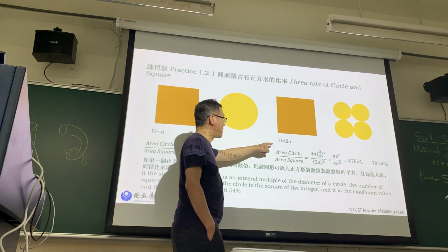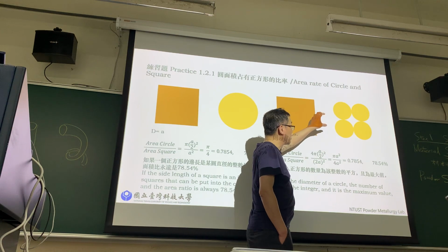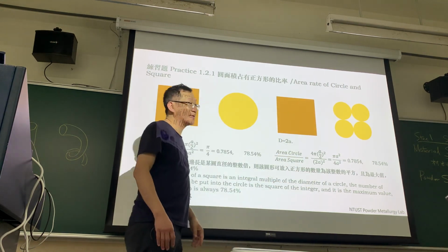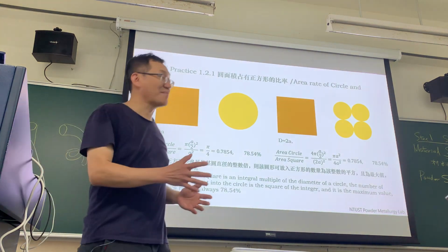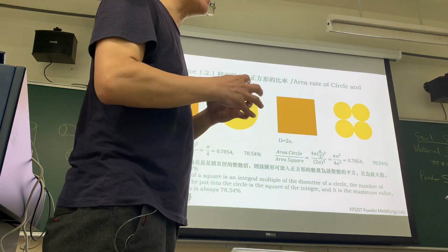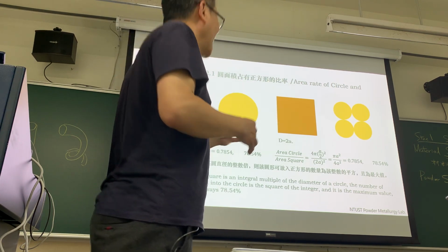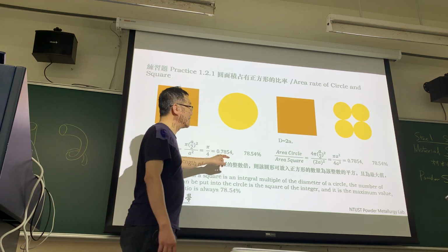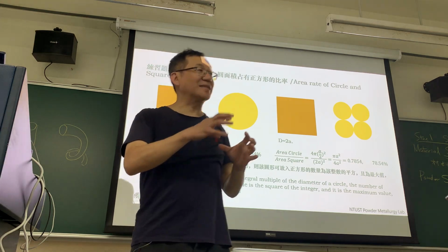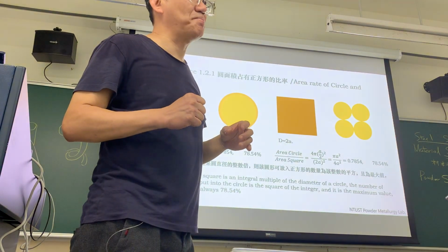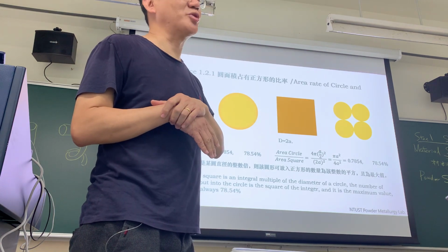So if D equals 2A, it means a small square, so we can put it in. Very interesting. This is true: the powder size, even the square, even the circle, is good. This means if you use this kind of shape and input it into the mold, it can only fill in about 78%. This is 2D. How about 3D?